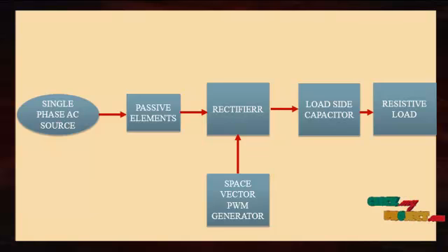And also we know that a rectifier is an electrical device that converts alternating current, which periodically reverses direction, to direct current, which flows in only one direction. The process is known as rectification. Physically, rectifiers take a number of forms including vacuum tube diodes, mercury arc valves, copper and selenium oxide rectifiers, semiconductor diodes, silicon controlled rectifiers and other silicon based semiconductor switches. Historically, even synchronous electromechanical switches and motors have been used for this process.